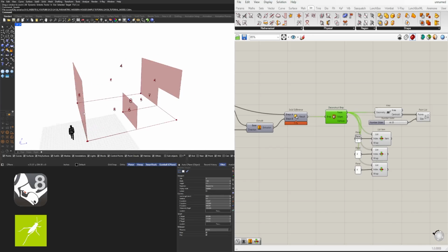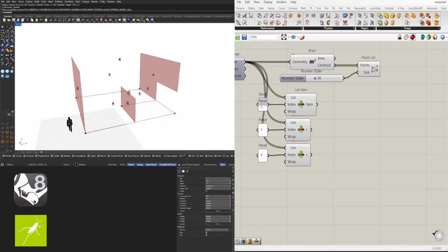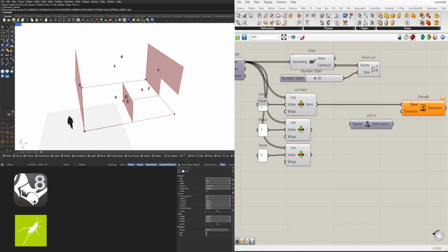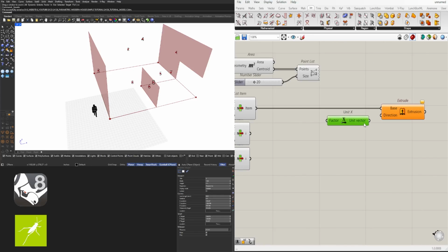What I need to do is extrude 3 in the X direction. So let's do that. 1 in the negative X direction. Go to extrude for 1 in the X direction. And the way that I see what direction I'm using is by looking at the X, Y, Z coordinate system here. So we're going to use -X. Now there's also a way to extrude perpendicular to that face, but there's a few other steps. And for now, we'll simplify it and extrude in the negative.